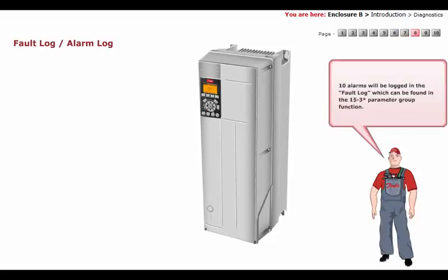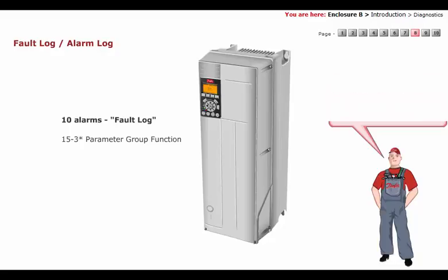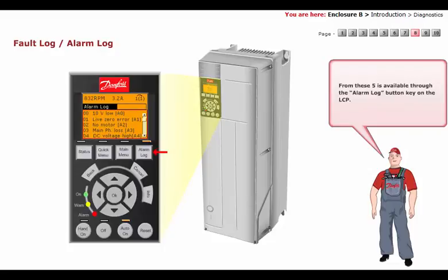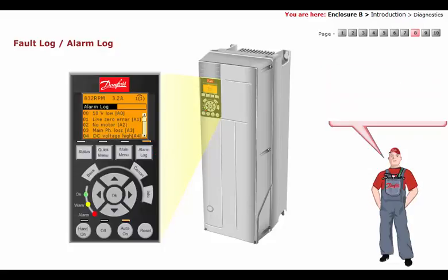Fault log, or alarm log. 10 alarms will be logged in the fault log, which can be found in the 15.3 parameter group function. From these, 5 are available through the alarm log button key on the LCP.